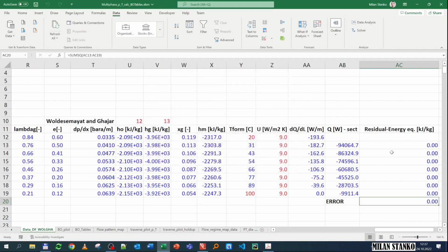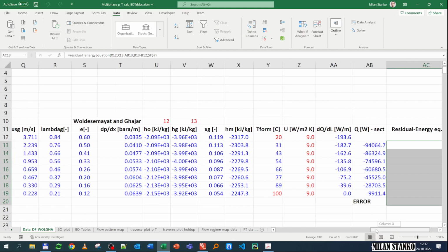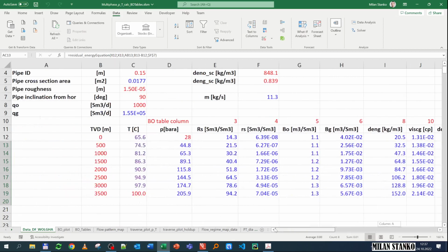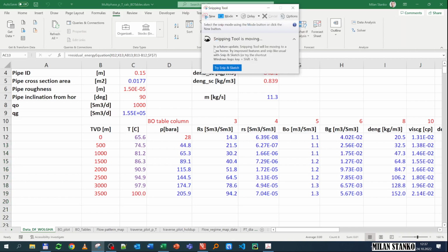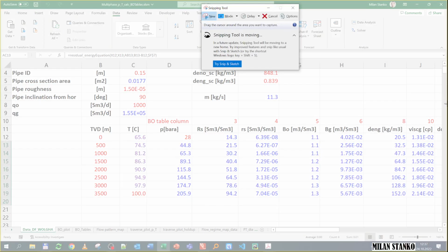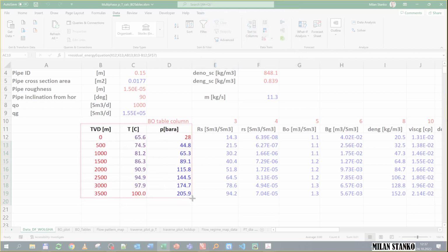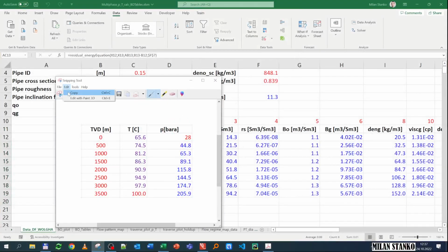Okay, now it finished. You see now all the energy conservation equation is honored. We have heat always leaving the fluid for all positions. Okay, and actually it's increasing from bottom up. And then you see this is the final temperature distribution. And let's see how it compares to the other case, where we assumed a temperature of 50 at the wellhead and did a linear interpolation. So that's my solution now.